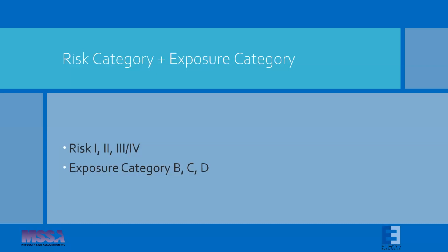So pressing a little bit deeper into the theory of signage design, the other two factors, in addition to the building code, that have arguably the most impact on design loads are the risk category and the exposure category. Risk category is ranked 1 through 4 and basically describes the use of a structure and how critical it is. Or to put it another way, what are the consequences to human life in the event of a failure of that sign? There are 3 exposure categories that essentially describe the surrounding topography and therefore how the local wind loads may be adjusted. It should be noted that there originally was intended to be an exposure category A, but basically the committee determined that a very heavily built up urban area with tall buildings was just too complicated to model, and that you would either have to do a wind tunnel study on your specific building or just assume exposure category B.